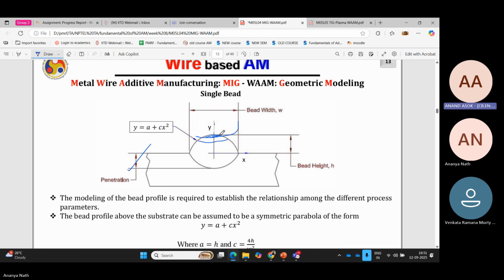In case of wire DED or powder DED, it can be one layer, but in case of other processes, like in case of LPBF, it's even 2-3 previously deposited layers, because there the laser power is less, but the spot size is even lower, and your layer thickness is very less. So it's around 2 to 3 previously deposited layers.